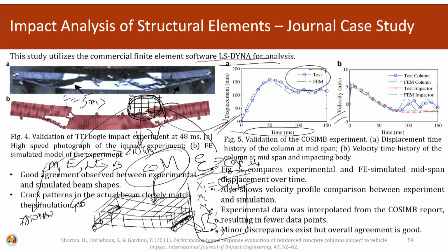If we run this using DYNA software, you will get this type of displacement and velocity curves. Then we can match this with any experiments, or we can devise our own experiment and do our experiments in a simulated fashion also, because doing all these experiments is very tedious.